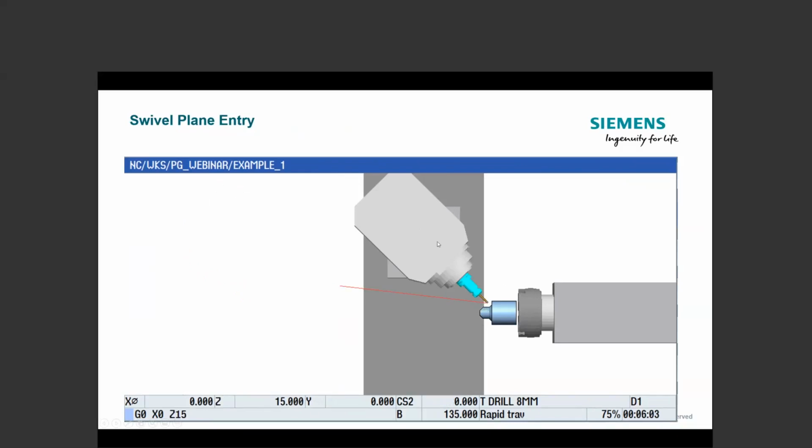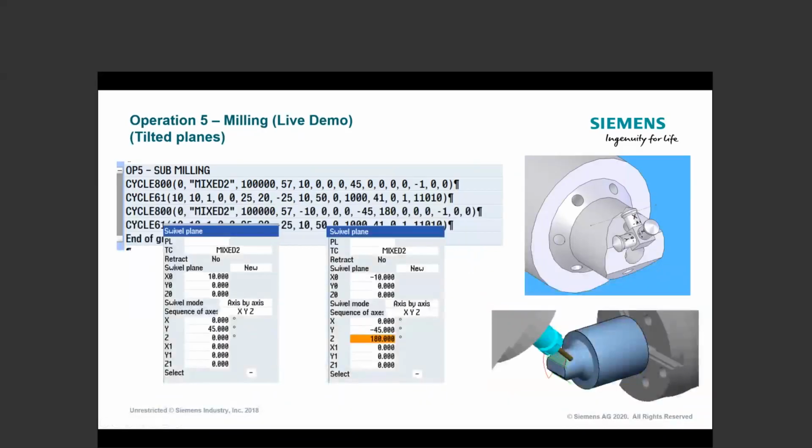That's when I can get to a crash situation. So that's just really being cognizant of the total distance from the center of rotation to the tooltip. Because as she swings around, I could potentially leave that tool and not realize it, that I'm lower than the part. And that's usually when crashes can occur for sure.